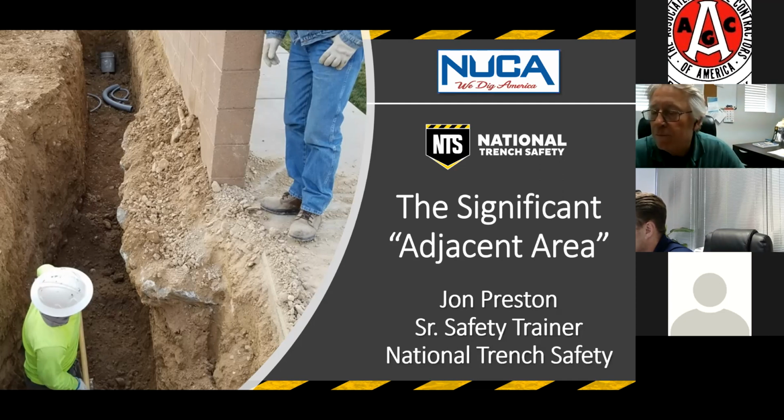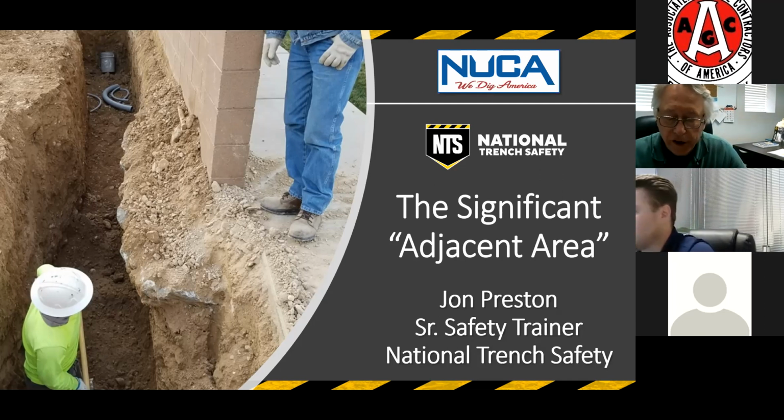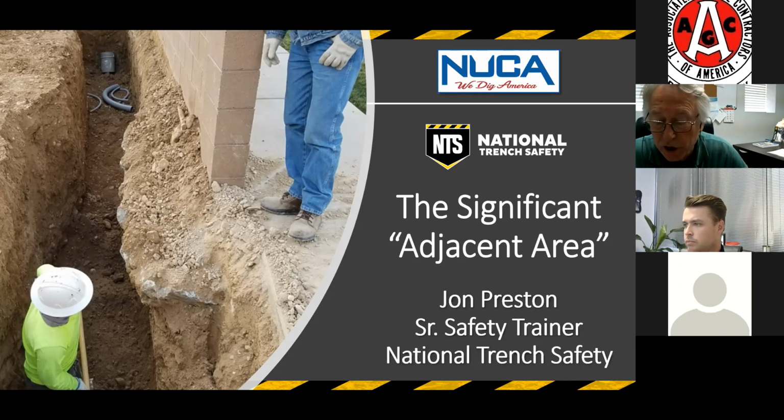Anyway, just to make sure there's no confusion, the principle of a shoring system, by definition, is that the shoring system prevents soil movement. Trench shields are different from shoring systems. They don't prevent soil movement. What they do is protect workers so the soil can fall against the shield and the shield takes that load. And so the worker inside the shield is protected from the falling soil.